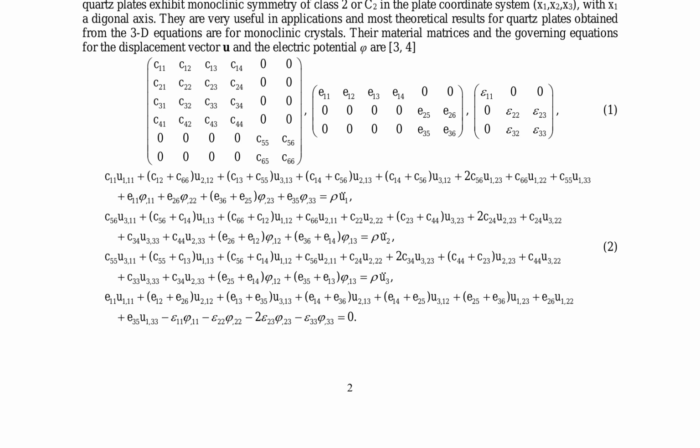The material matrices and governing equations for the displacement vector U and the electric potential phi are detailed, including the stress and electric field components. These equations highlight the anisotropic properties of quartz, demonstrating how they contribute to its unique characteristics. The study of these properties is essential for optimizing the use of quartz in various technologies, such as oscillators and